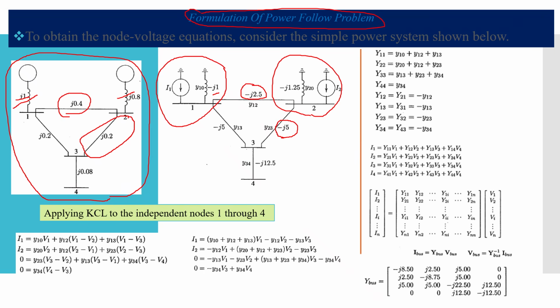So to proceed to the power flow analysis and obtain the power and the current characteristic equation as a function of other electrical components like voltage and the voltage angle, we will perform a KCL for each bus. For example, for bus 1, we have I1, which is the magnitude of a current injected from a generator to bus 1.